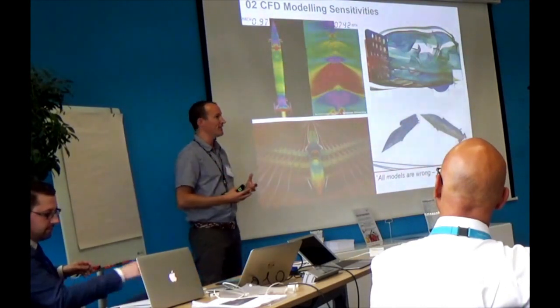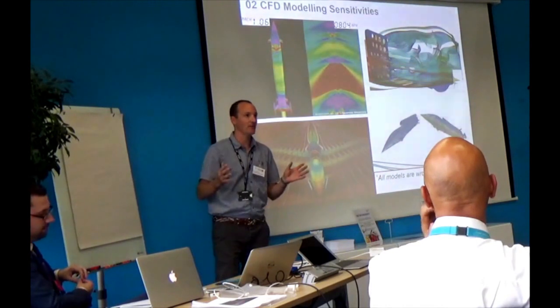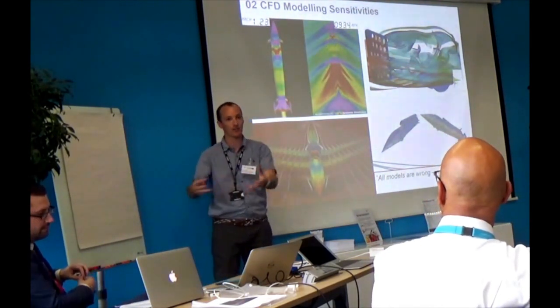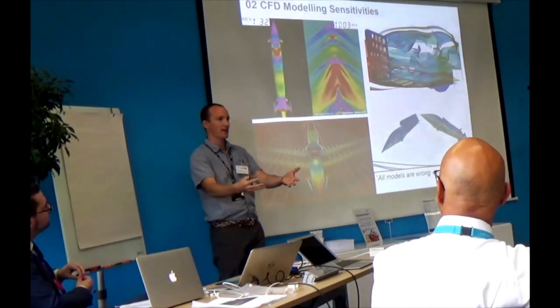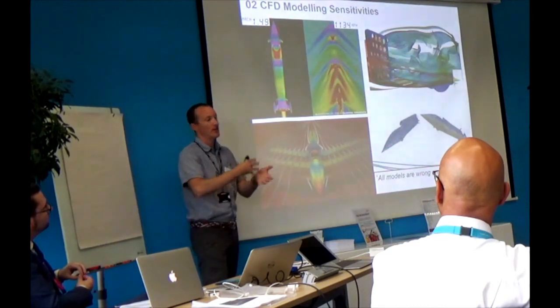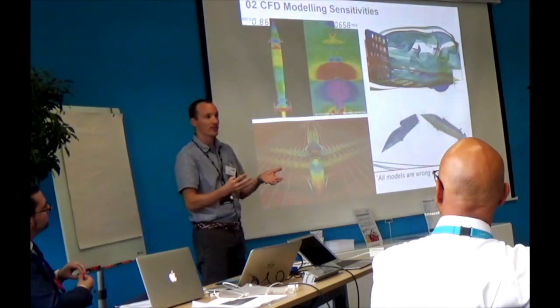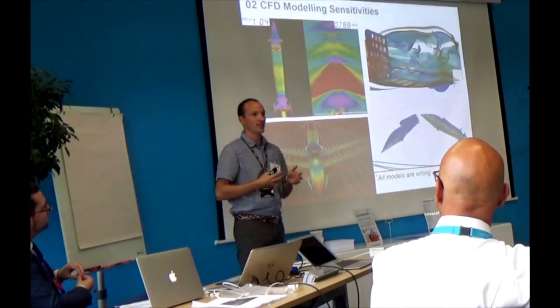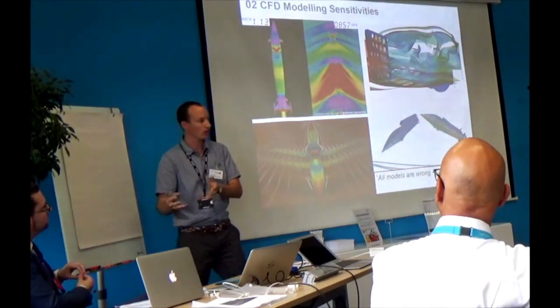The problem we have is no data exists about how supersonic rotating wheels interact with the kind of surface we're going to experience on the Hakskeen Pan in South Africa, how much of these particles will get entrained into the flow. And one of the things we've noticed already from running these models is the assumptions you make about the amount of particles that get entrained into the flow have a big influence on the prediction of the models.